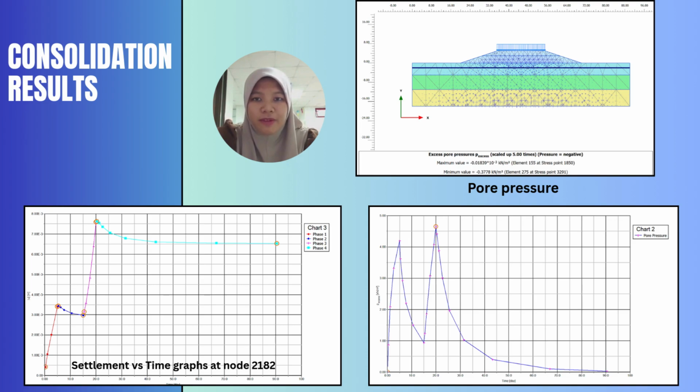The settlement time graph indicates rapid settlement during embankment loading, followed by slower consolidation settlement. The excess pore water pressure increases during construction and gradually dissipates with time, confirming time-dependent consolidation behavior of the clay foundations.